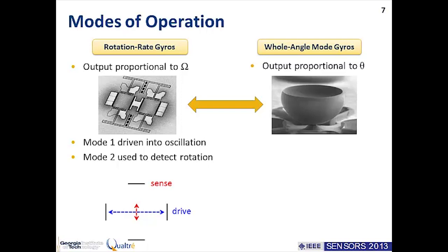And then we apply rotation. Obviously, part of the energy that we inserted into that drive mode transfers into our sense mode, and then the amplitude of that vibration in the sense is proportional to our rotation rate.